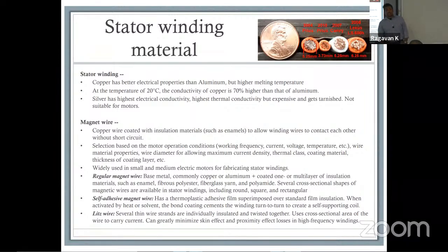You can also have designs, and that's something that's been extensively looked at in terms of a trade-off between cost and design complexity. You can go for a round, you can go for square, or you can go for rectangular winding. Oftentimes you will see people talking about doing rectangular winding because round by definition leaves out space, right? So which means you have gaps in between your wires that are bunched together. Square or rectangular, on the other hand, can actually sit next to each other and give you much better fill factor. You have to remember what we had just a comment a little while back, if your slot is curved at the end, that means now you're going to end up with a square shape that might have a difficult time fitting into your slot.